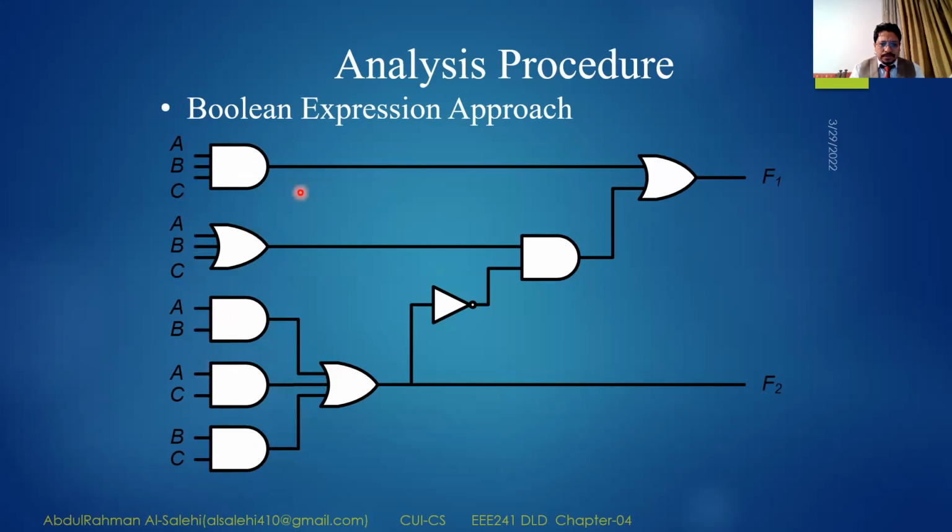I have this circuit. Let's say the output of the first one, which we call T2, what is the output of this AND gate? It is ABC. Simple as that. And we have done this in chapter 2 and chapter 3 as well. So let's see again for the other ones, for A, B, C, when we OR them together, meaning that I'm going to sum them, I will just add a plus between them. So again, it's very simple when you define your work and segment it.